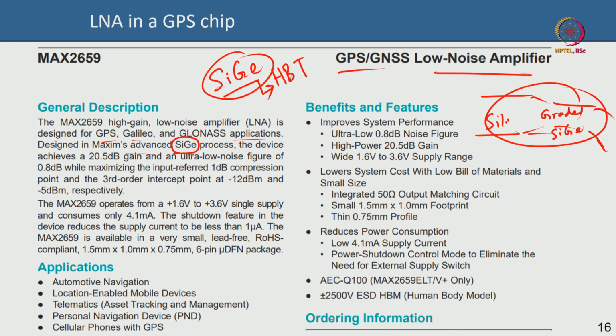The silicon germanium HBT is fabricated in a CMOS process along with the rest of the chip, digital or logic or other things which are CMOS based. So this is called a bi-CMOS process many times, because you have a bipolar device which is a silicon germanium HBT, and that is useful for making things like LNA, correct, in the RF radio frequency domain. It coexists in the same wafer, probably it coexists in the same lot along with digital, logic, memory, other application chips which are based on purely CMOS. That is why it is called a bi-CMOS process.